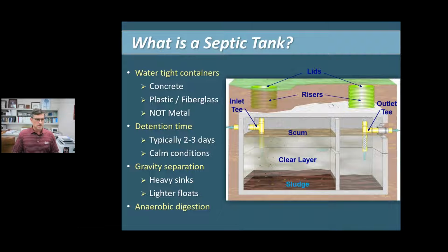When we think about detention time, typically a couple of days, 3 days, this is one of those pieces that I feel can be an impact when we talk about hydraulic loading, the amount of water that's actually getting put into the system. And for those of y'all on here that may be familiar with large scale wastewater treatment, whether we're talking about a lagoon or a mechanical treatment plant, they're really no different.